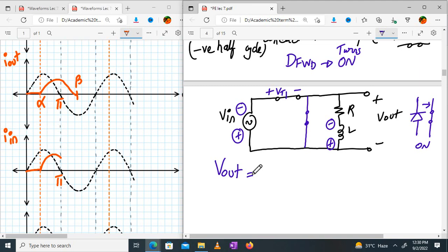Look, where is that short circuit coming? Is it coming in parallel with the output? Yes, na? What is this short circuit? It will come in parallel, so output will be zero. Does it make sense? Did you understand how the output is 0? Because the diode turned on, your freewheeling diode is on, the output becomes 0.